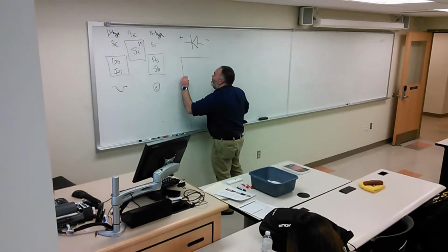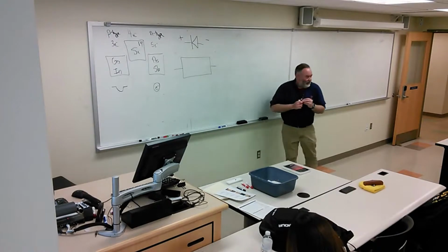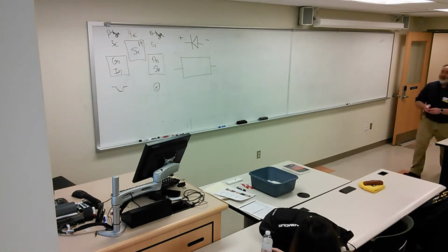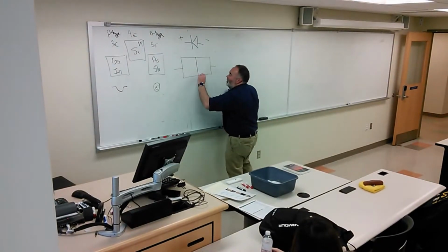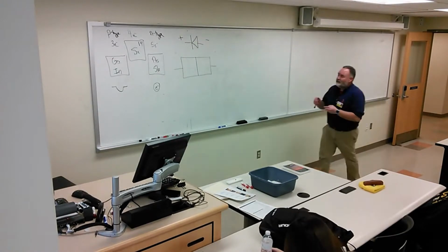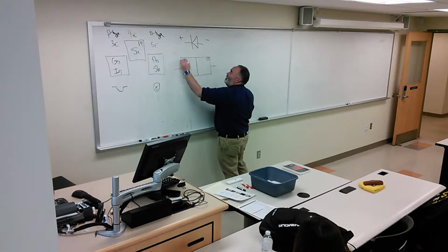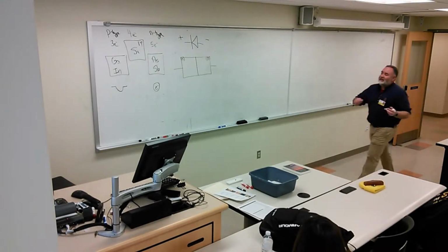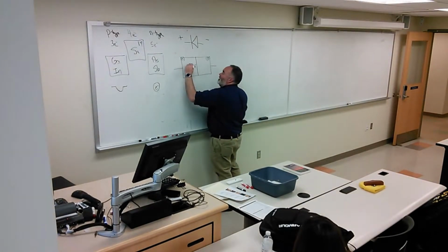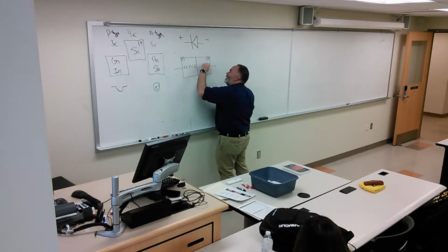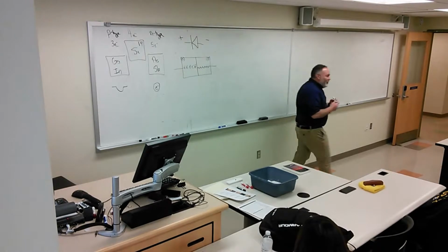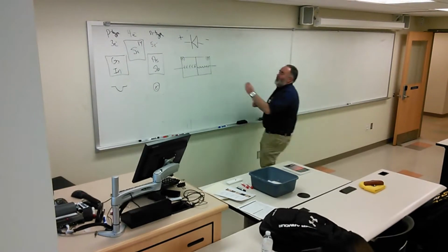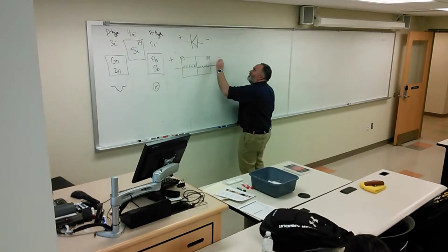And we said if you take a look at the actual construction of the diode itself, and you look inside, it's obviously a simplification, but it's an accurate simplification. This is not fiction. This is a good description of it. We said inside here we're going to make this diode out of these 2 different types of semiconductors. We're going to put the p-type over here, and the n-type over there. The p-type has these spaces, the n-type has these electrons. So here's the electrons. And over here is my cartoon of little tiny parking spaces or empty spaces for the electrons. And if we look at this from the perspective of the electrons, that's not a C, that's an E. Here's positive over here, here's negative over there.